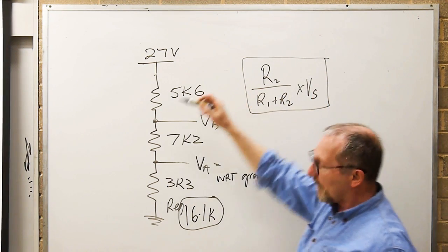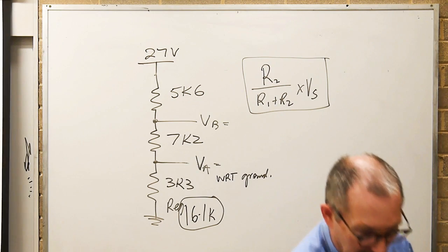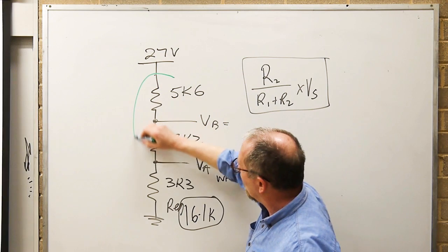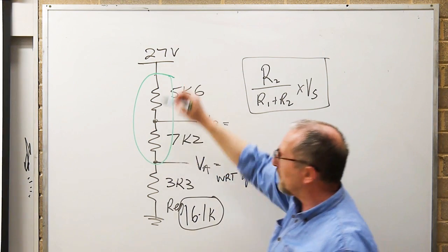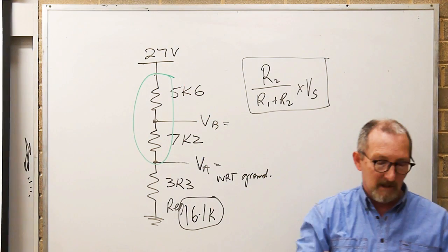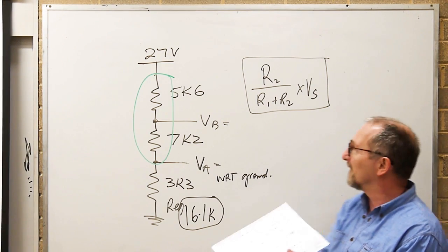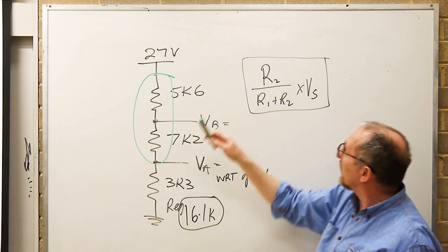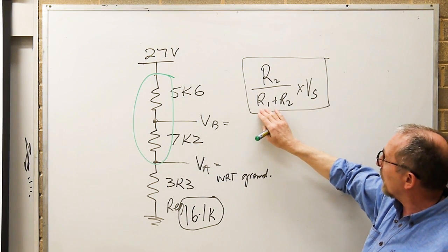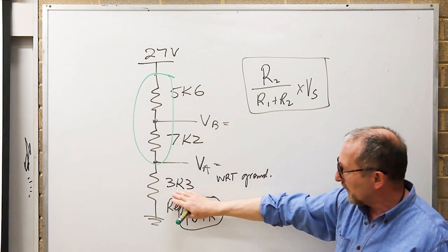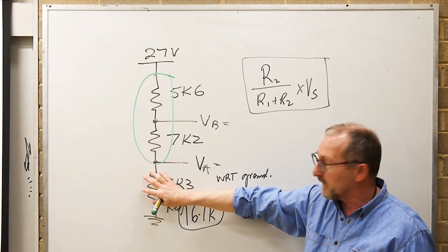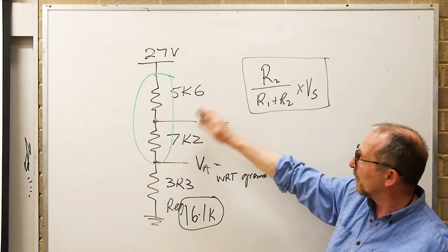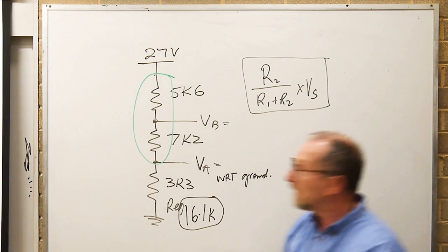And then I would be, with a different colour, lumping those together. I'd be putting a circle around there, and remember, I've got to get R1. I know what R2 is. R2, I'm calling that 3.3K, but R1, I need to add those two together. So what's that going to be? 12.8K. Yeah?